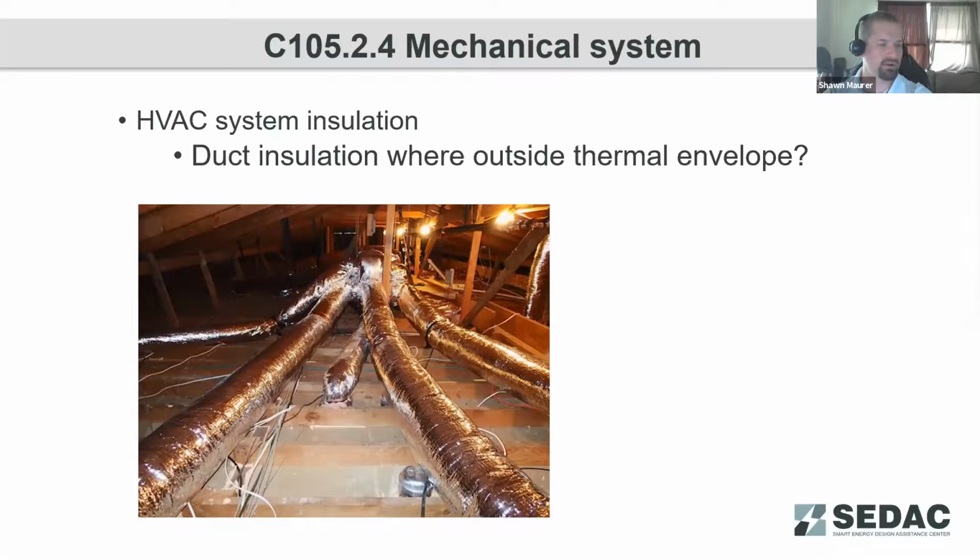For any interior unconditioned spaces, such as chaseways, outdoor vented mechanical spaces, tunnel systems that might be semi-conditioned or unconditioned, again, checking that insulation has the proper insulation values on it. And for commercial duct systems, duct sealing is required. However, duct testing is not required, at least not yet.